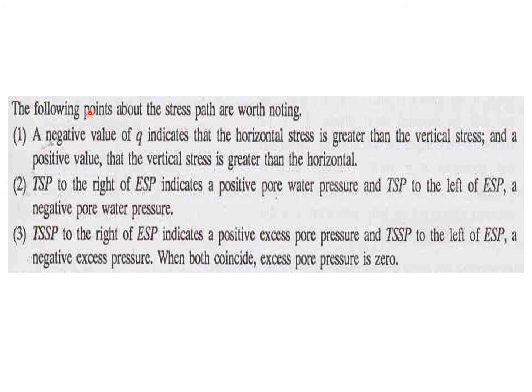This slide is very important. The following points about the stress path are worth noting. Number 1, a negative value of q indicates that the horizontal stress is greater than the vertical stress, and a positive value indicates that the vertical stress is greater than the horizontal.